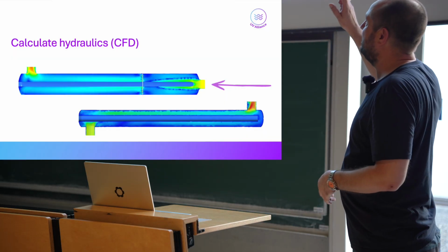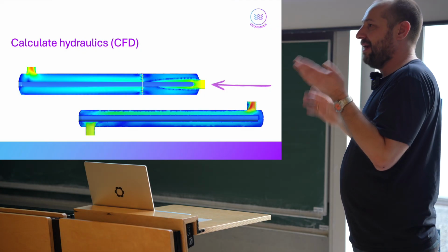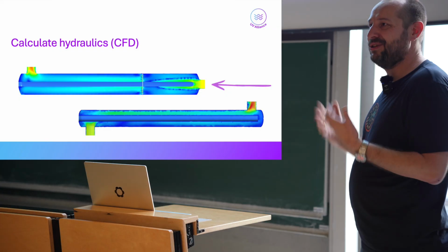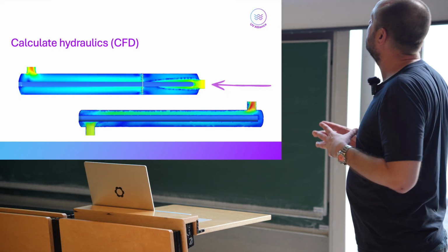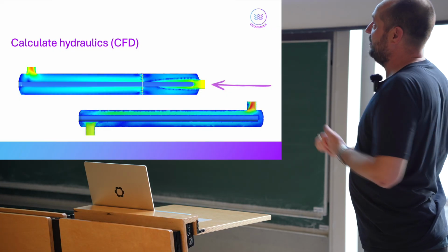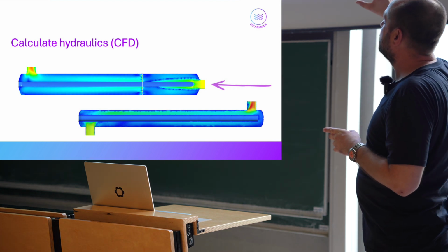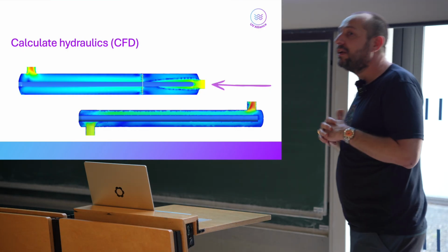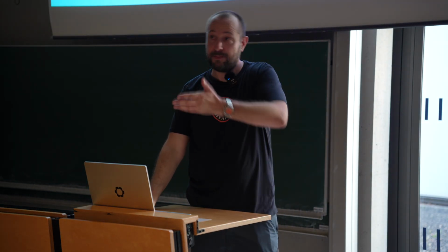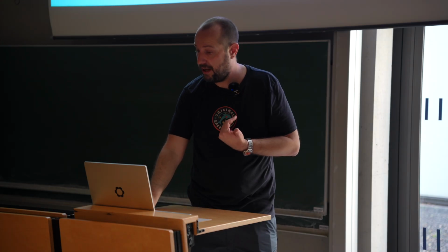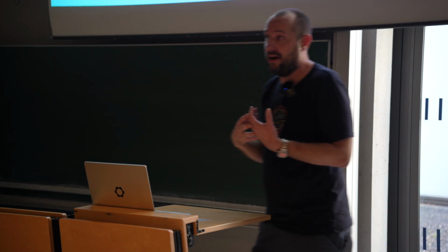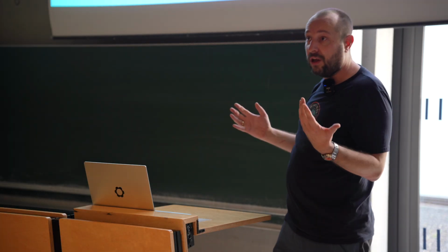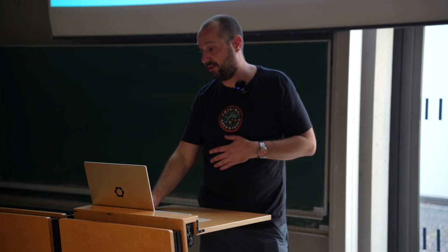And you can idealize that up to a point where your minimum and your maximum UV dose are very close together. And that means all your light is used the way you want it, reaching a similar dose. And this makes a big difference in efficiency. I would say the efficiency difference between these two approaches can be significantly more than 50%. So that's pure savings in energy. And that's important because the main operational aspect of UVC systems is energy consumption. So the lower you make it, the better your system is, the more sustainable your system is.